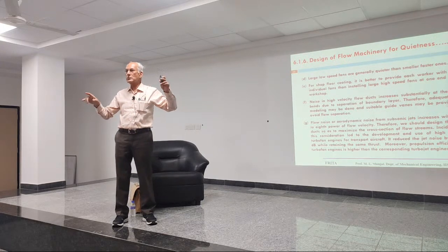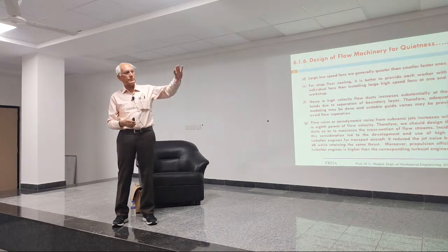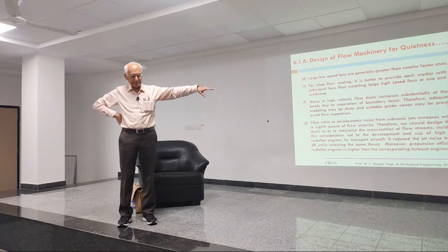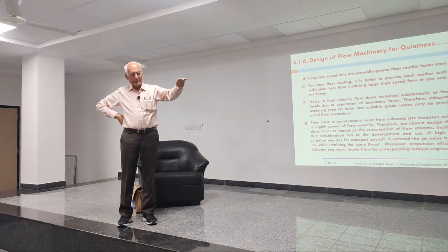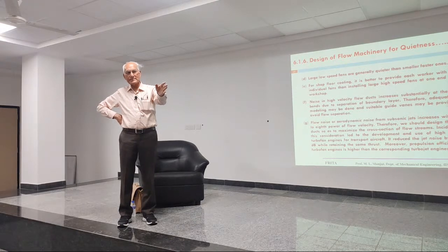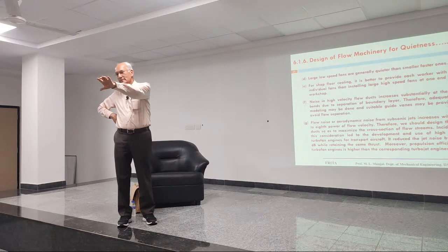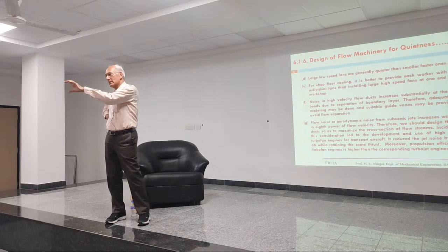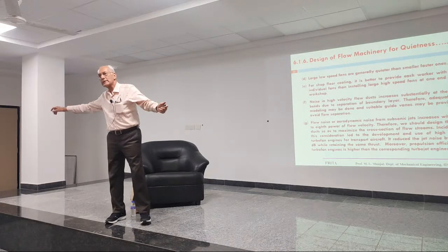In those days, you did not have bypass engines. You had, for example, let's say, the inlet, then you have a low speed compressor, high speed compressor, and then you have the combustor, then you have the turbine, HP turbine, and then you have the expansion nozzles and the thruster.